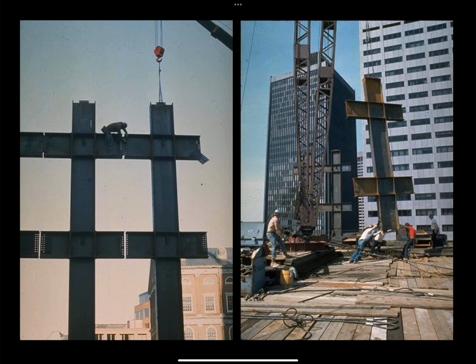And then the joints between the elements vertically are made about 4 feet above the floor, not at the floor level. This is to simplify the joint. And then the joints horizontally are also made at midspan rather than where the column and beam come together. Again, this simplifies the joint. So these are prefabricated in 2-story high elements.